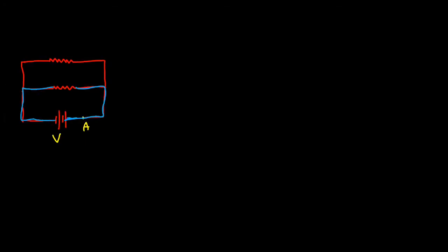This one is a parallel circuit. Again, I want to study Kirchhoff's voltage law for this parallel circuit. So I start again from point A, and this is our battery that gives us, let's say, voltage V. So we need to write Kirchhoff's voltage law for every single loop. So I start with loop 1, and I just try to show it with different colors. Okay, we start writing Kirchhoff's voltage law for loop number 1.